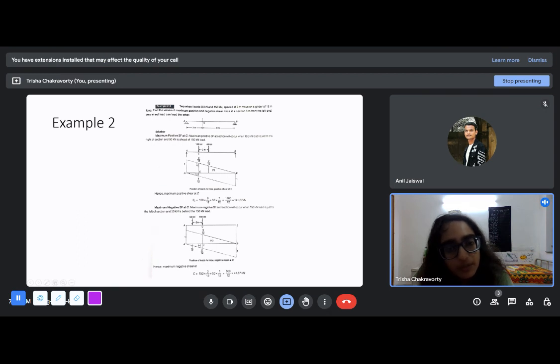On the other hand, if you put it like this, that 150 is here and the 50 is here, it will give the worst positive moment. And this you have to understand logically. You cannot calculate it by putting it everywhere. Logically, if you have a series of wheel loads, you put the heaviest wheel here, and the second heaviest, the lesser heavy wheel, on the other side, where it is also positive.